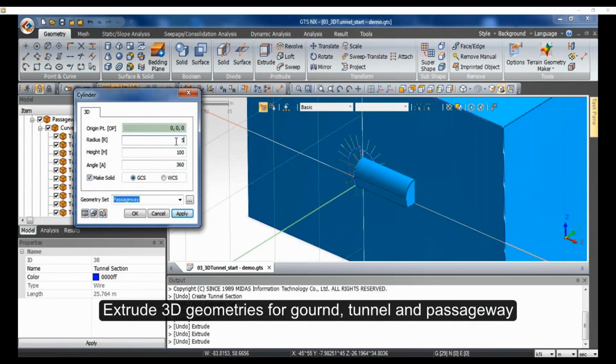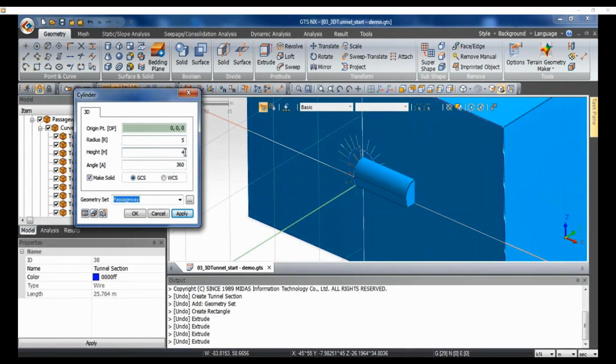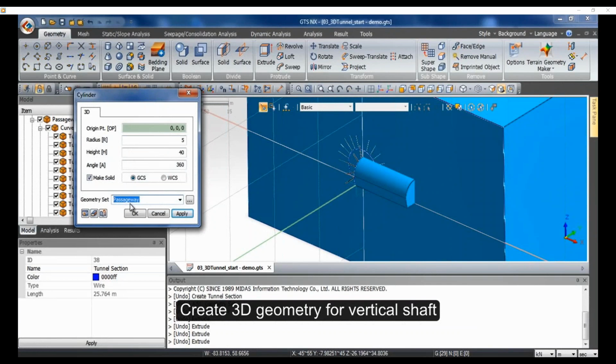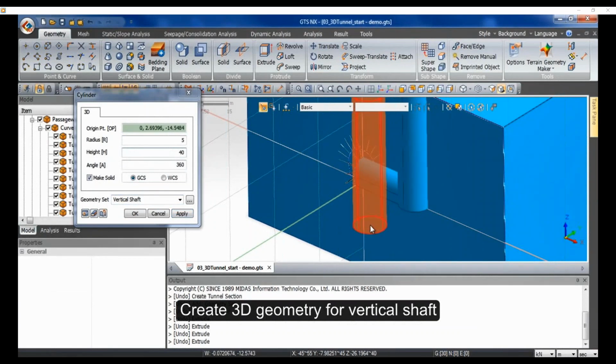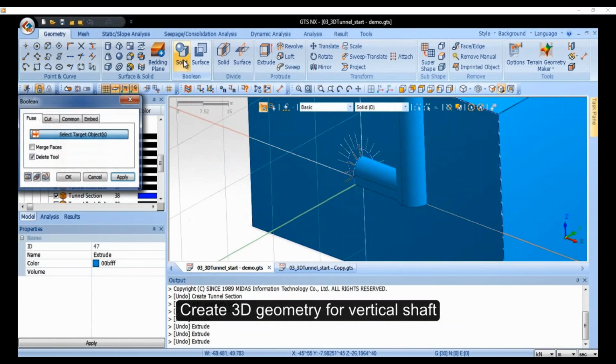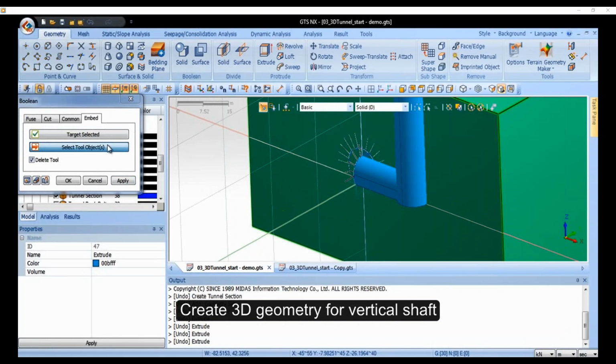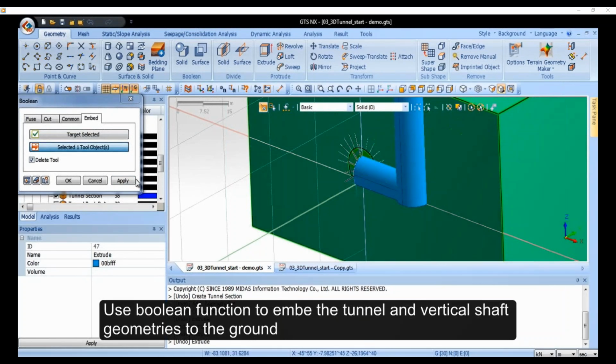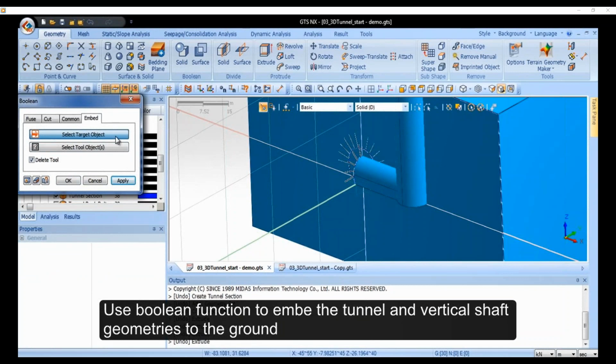And the last is going to be the shaft, the exit shaft. For this, I'm just going to create a cylinder solid. So I know the coordinate location. I'm telling it the dimensions. It's a 40 meter shaft with a diameter of 5. And I can draw it into my model, and it has an option to lock things into place. So these tunnels have now connected at the base. Now I'm telling the program this tunnel is inside of this solid, and repeating the process for the other sections.